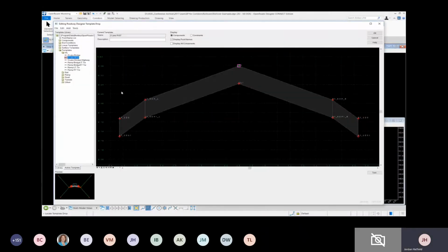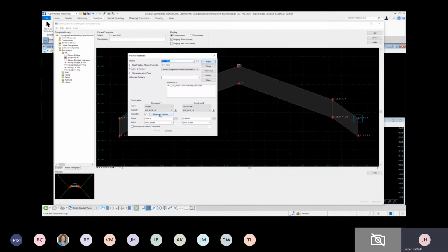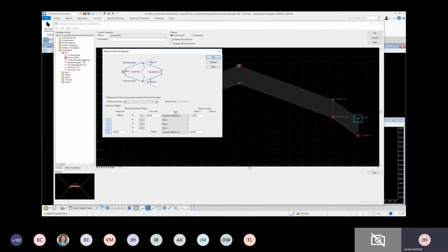Okay, let's look at an example of this rollover enhancement. In this case, we have just a simple shoulder situation, similar to what we would have in SS2. So let's look at the right edge of shoulder here. I'm going to slide this to the side, rollovers, and just get directly into the rollover tool. You notice the different dialog. Obviously, that's one of the things of note.